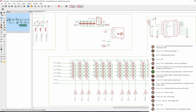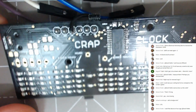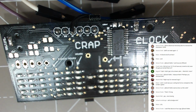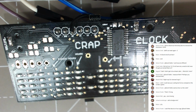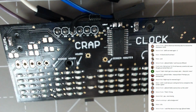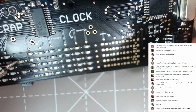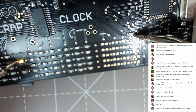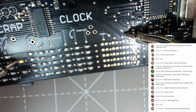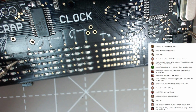I'll tell you what I can do. Let's go back to the main cam, and I'm going to disconnect from the microcontroller for a little bit, and we're just going to poke around on the diode mode on our multimeter and see if we can light it up with the LED in series with those two bits. So it is power over here. If I pop that here, and hopefully you'll be able to see the resistor, I'm going to poke on just over here. So it does work. It is lighting up. So it is connected, and it should be connected to one of these over here.